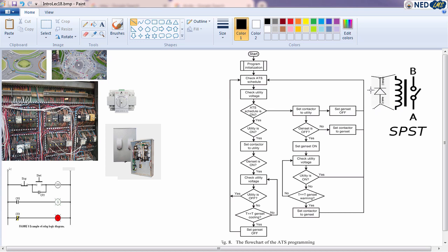So we always attach a diode for a DC relay, so that whenever the 5-volt supply is off and the coil de-energizes, it's going to develop a back EMF in the reverse polarity, and the resulting current due to the extremely high voltage spike is going to circulate inside this winding, because the diode has very small resistance, in milliohms, and the winding also has a very small resistance.